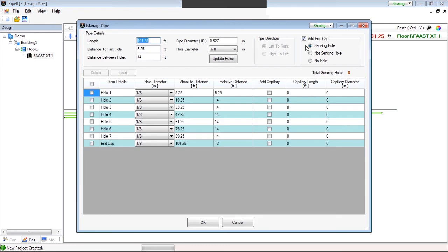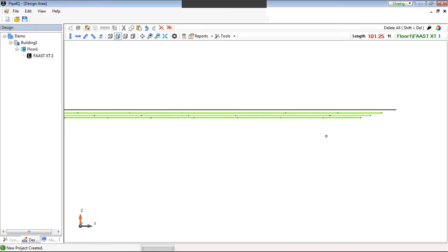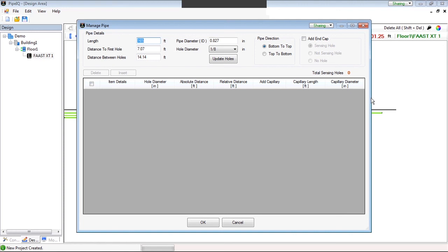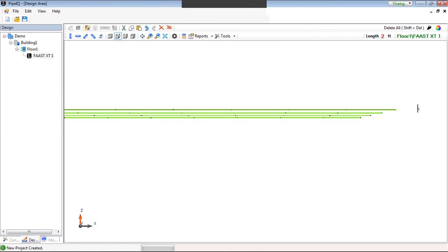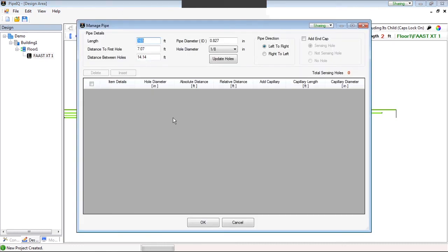We have to remove the end cap, because we can't connect the pipe to an end cap. So we remove the end cap. So we now select the piece, here's our manually adding parts. So we're going to add a pipe here, and we're going to go down and around that ductwork. Let's say it's a 2-foot ductwork, and we're going to go top to bottom. So we have a pipe. You can either clip the pipe and drag it, and it'll snap into place, or as I mentioned, you can use this connect pipe tool. So now we're going to go around that ductwork. So I'm going to say 2 feet from left to right.